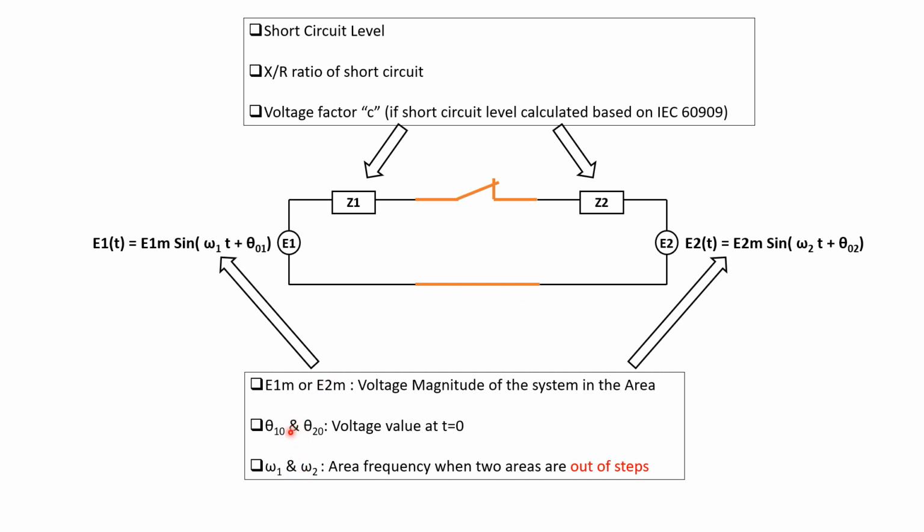The frequency difference is not very important in terms of these parameters, because different frequencies mean a time-varying phase shift between the two sources. But anyway, we need to know that. Normally the role of these elements is mostly when we have a fixed frequency, and also two different frequencies in the two systems because of out of step and loss of synchronism.